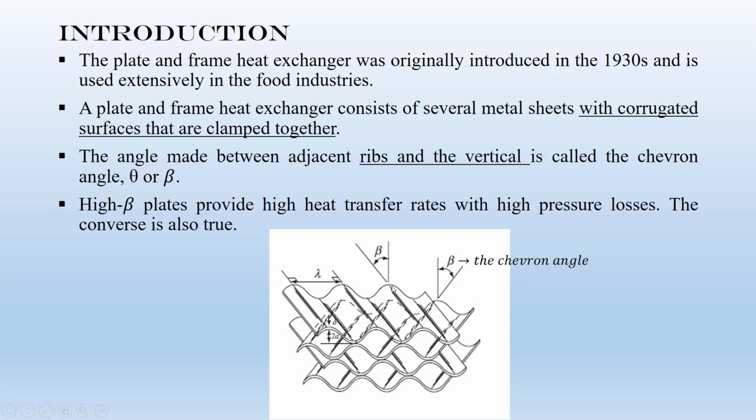In some textbooks this angle is called theta, in others, beta. This is really important because a higher beta means a higher heat transfer rate and a higher surface area. However, at the same time, a higher beta means a higher pressure drop, or pressure losses.